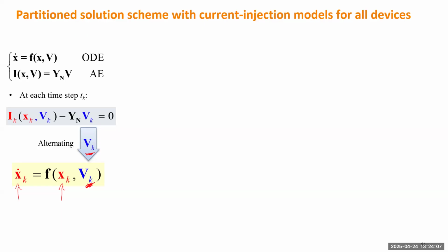Then the simulation gives the change in the state variable for one time step, and you give that value back to the network. The network uses this state variable, maybe for some control, to update the power flow solution and solve the voltage. Then you go back. After one cycle, you finish one iteration, and for each time step you need to do such an iteration.